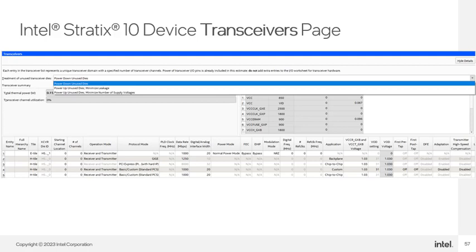Tile options are available depending on the device selected on the main page. At the top of the page, you can select a general option for how unused transceiver dies should factor into the calculation for devices that include H-tiles. Unused H-tile transceiver dies can be active, but in low power modes based on the selected supply voltage, or they can be shut down entirely.